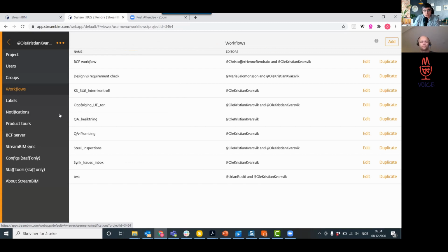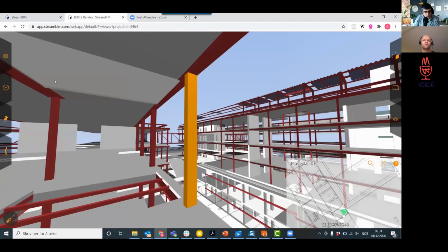Yes, we have. I'll briefly mention it, but StreamBIM is a BCF server, so we can use Solibri to create issues through their live connector. So they are set up as a client and StreamBIM as a server. They just released an official version supporting that from Solibri's side.